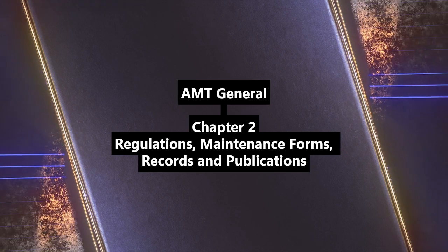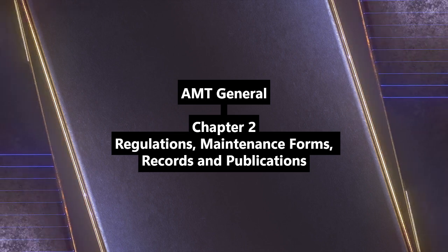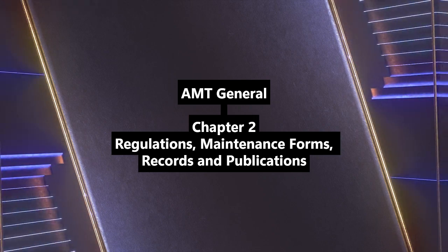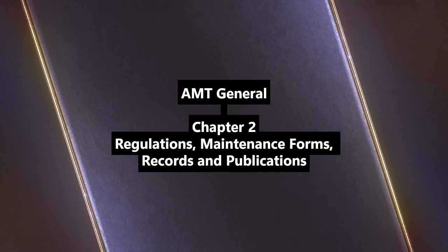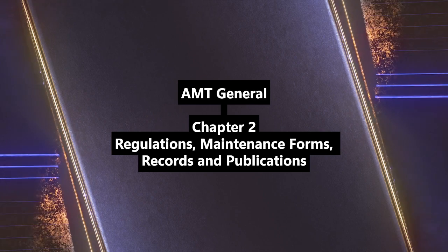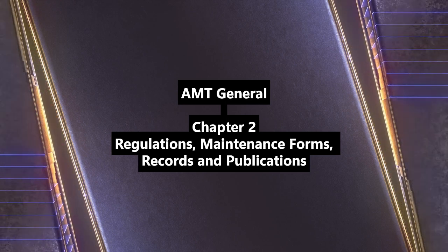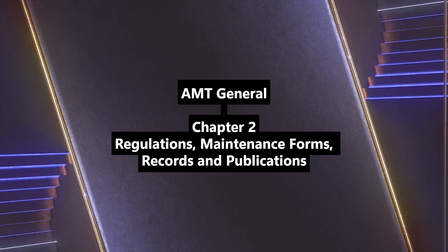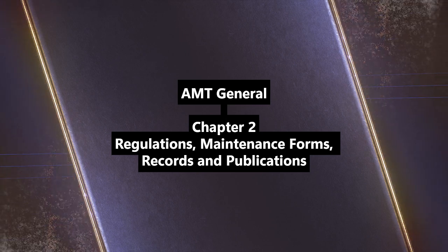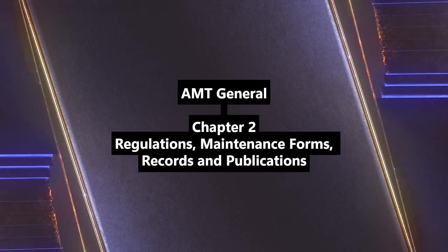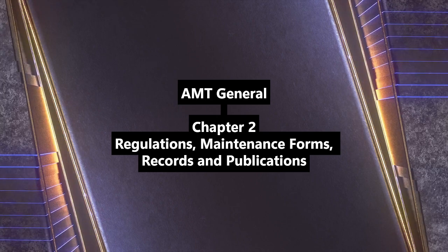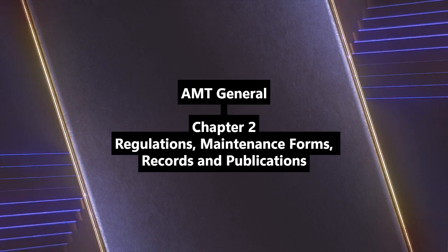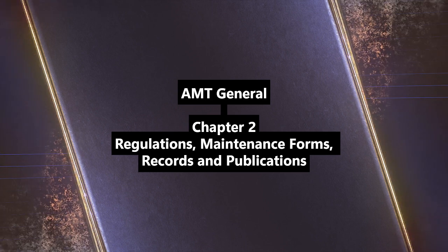Okay. Section 43.15, more performance rules specifically for inspections. Covers details for rotorcraft checks, annual and 100-hour, which must use a checklist covering the Appendix D scope, check engine performance, and progressive inspections. What are the key points for progressive inspections? Must start with a full inspection, breaks big inspections into smaller tasks, defines routine versus detailed, requires IA oversight, needs an FAA-approved schedule, allows a 10-hour en route extension, intervals can change with experience, and reverts to annual or 100-hour if stopped. Can inspections be done away from the main base? Yes, by a rated mechanic, repair station, or manufacturer using the original program's procedures and forms.